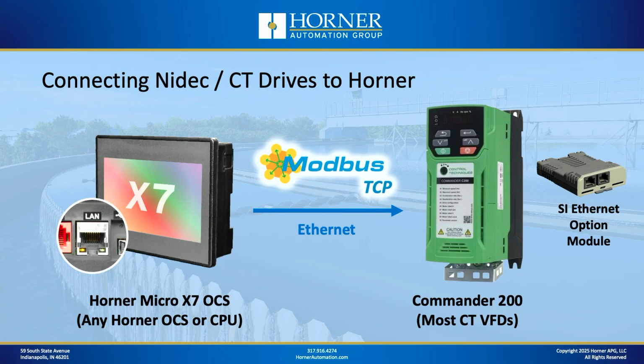Now, in terms of connectivity utilizing Modbus, of course they support Modbus TCP, which is certainly supported on the Horner product line as well as a lot of other PLC manufacturers. If you do want to utilize Modbus TCP, you will need an Ethernet option module for your drive, but they are available depending on the drive series you're using. Although I believe the high-end drives do come with Ethernet built in.